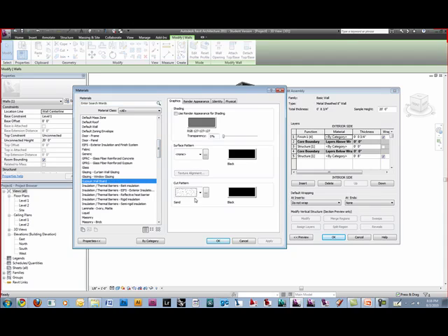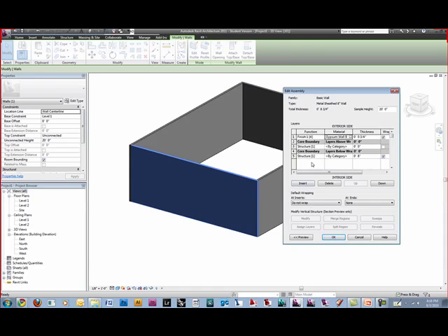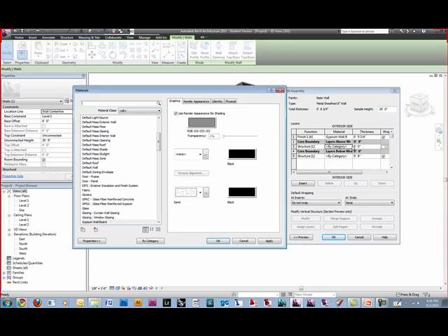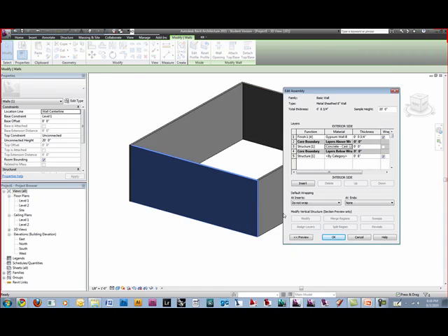So what are we doing? We'll do gypsum wallboard just for that one, because that's normally what goes on there. And then for this one, we're actually just going to make it probably concrete this time. And then the bottom one is going to be the finish layer as well. I like to distinguish finish layers 1 and 2, so I still know which one's exterior and interior. I just made a mistake. We don't want gypsum wallboard on the exterior side. We want to move it down, and then this one we'll move it up. The thickness we'll do maybe a 1/2 inch for the exterior.